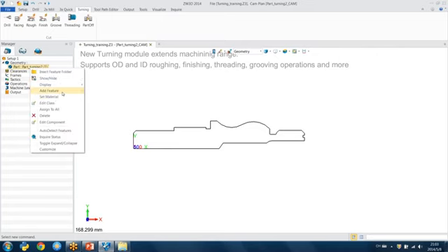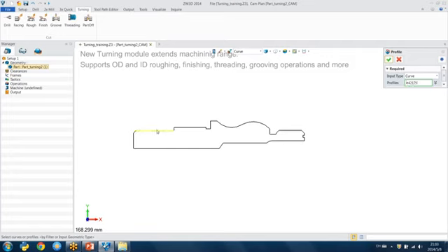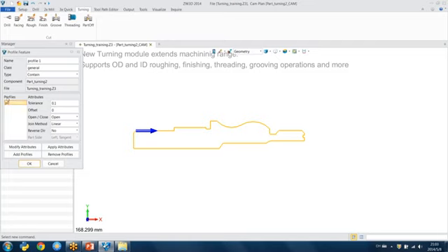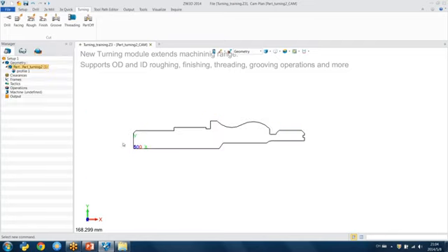So with this part, I need to add a profile. Choose all of the profile. Just press Shift and click. It will choose all of the keycaps. And press OK. Change the type to part and check the direction of the profile. Okay, it must be counterclockwise. So I should change the direction and press OK. So now I correct the profile.